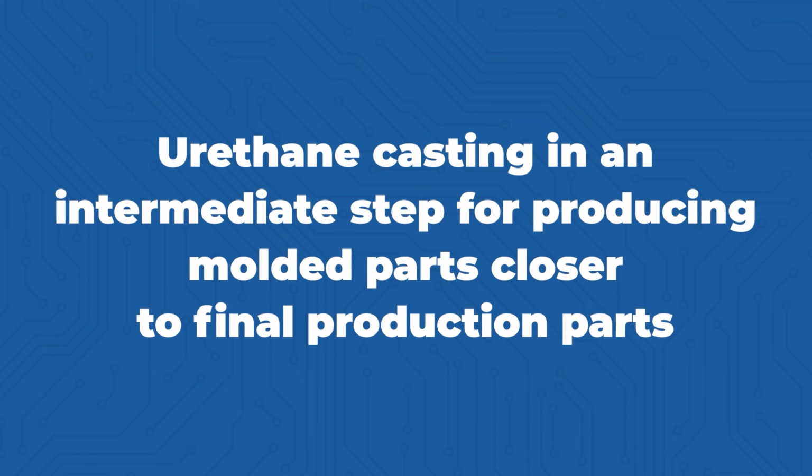Urethane casting starts off by, first of all, you take a 3D print version of your part or a CNC machine version of it. That's how it starts. Then they take that and they basically, using that, they build a mold out of silicone. Silicone is soft, rubbery. They build a mold out of silicone using your 3D printed part. You will end up with a mold that has a cavity in it. First of all, the mold's made out of silicone and it will have a cavity that's the shape of your part. Then they can put urethane in that mold and form molded parts of your product that are made out of urethane.